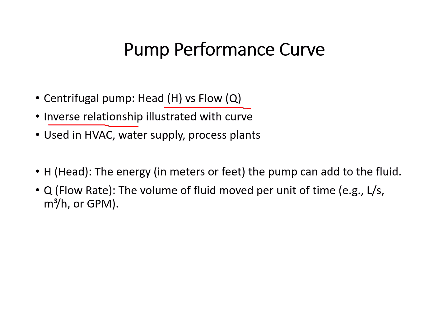The curve that we will see shows the relationship between the pressure the pump can build, which is the head, and how much flow it is producing. So it's like a seesaw, as I just told you. More flow, less head. Understand this and you are halfway to selecting the right pump.